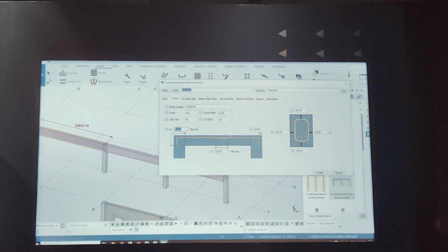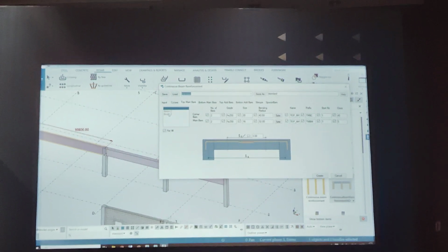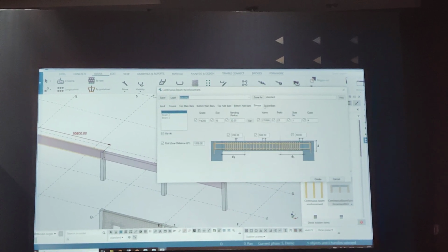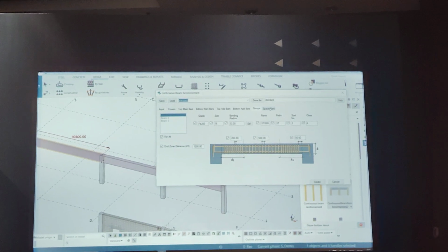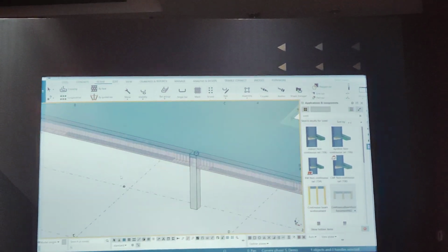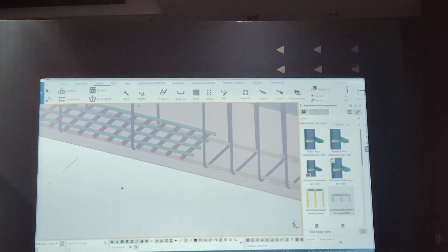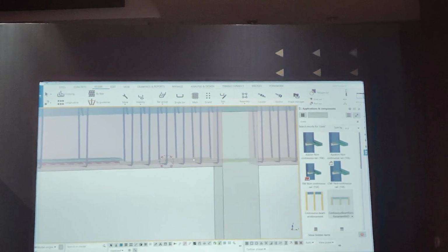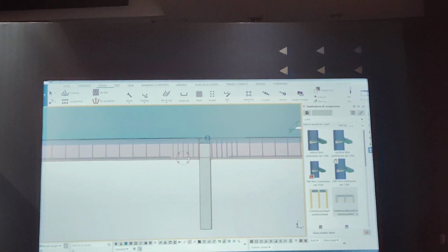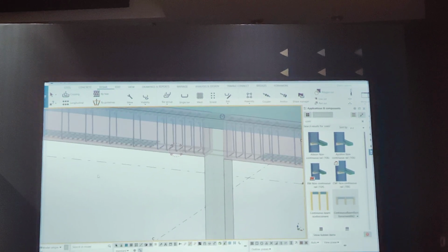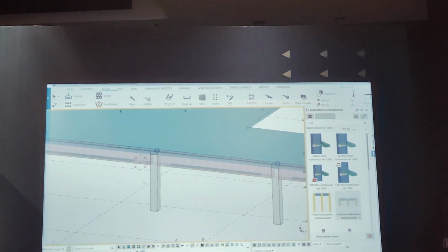And here we have the development length values. We have for each span what is the main top or bottom bar, I can specify, and additional bars, stirrups and spacer bar I can specify. Then create. So you will find your reinforcement created with crank lapping according to that location where you specify. Even if there is a change in depth of your beam, your bar gets terminated and then Ld will be extended to the next bar.